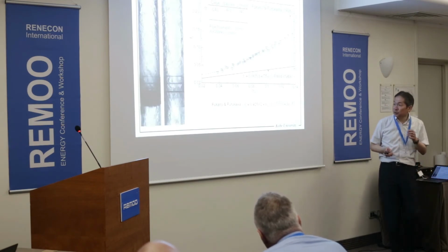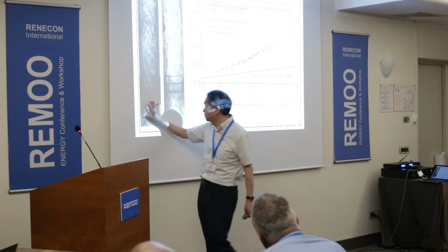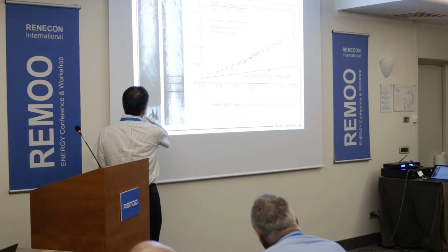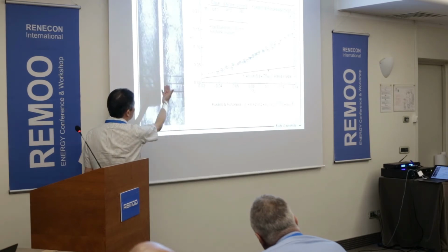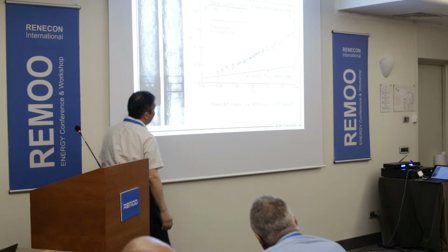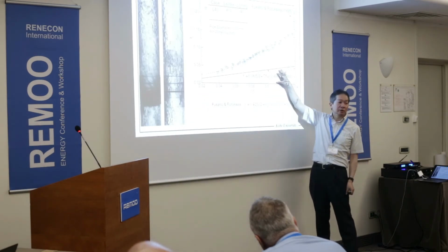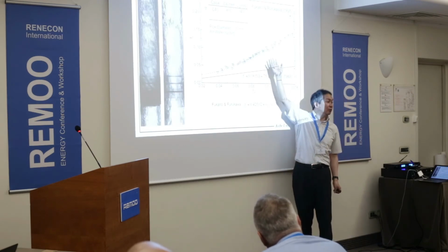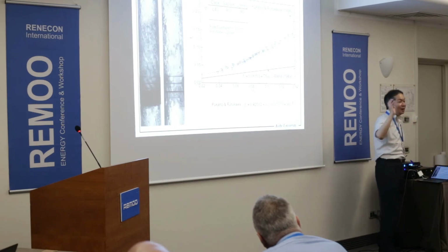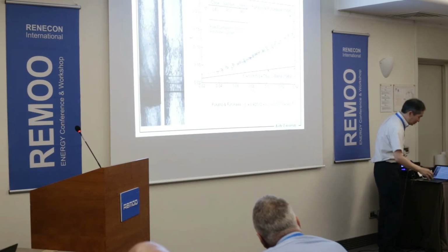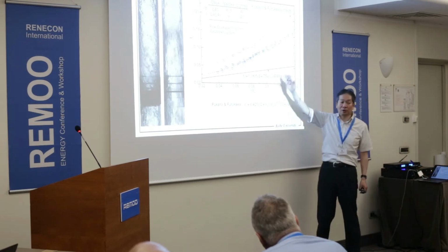In the beginning, I showed the swirling flow in the steam separator of the boiling water reactor. Here I put the swirl, so the flow is swirling. And here it's a standard annular flow without any swirl. In the case of non-swirling flow, Wallis's model doesn't work well, but Fukano's model works very well. So you cannot use Wallis's model, although we have relied on it for many years. In the swirling flow, again, the data is far different from the Wallis model.